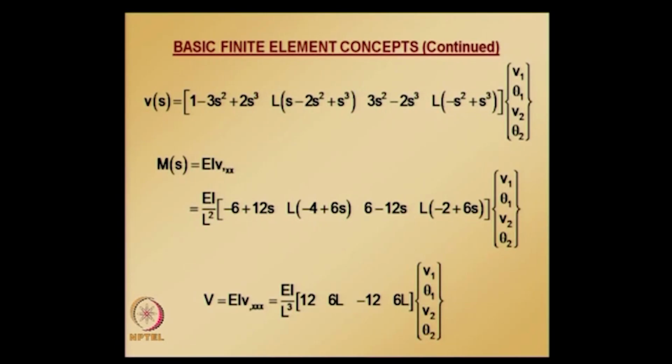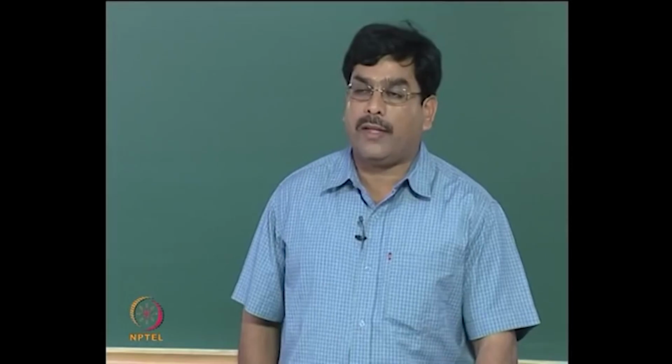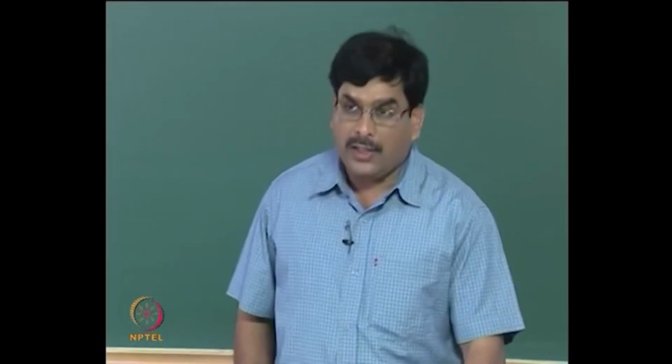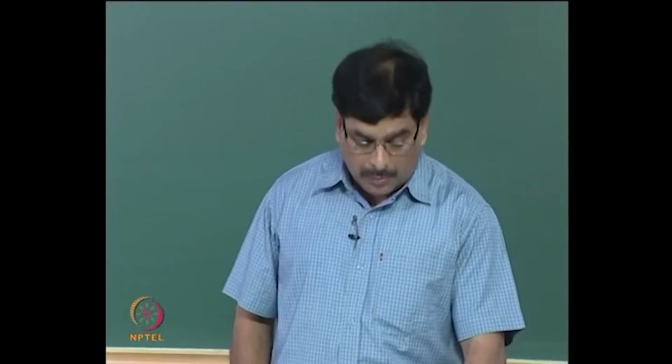Therefore, analysis of continuous beams in which cross sectional properties do not change in a span requires nodes only at the supports and under the concentrated loads, whereas non-uniform beams, for which EI is not constant throughout the length of the beam, require more elements per span for better accuracy. These are things we need to keep in mind when solving beam bending problems using the finite element method.